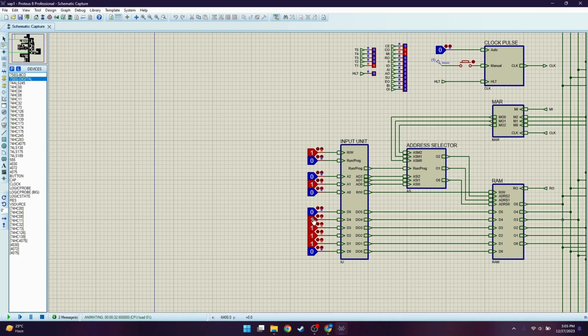Then we go to the next address location, and I will select the next opcode, which is 011. The next 3 bits don't matter. Still we are making them 011, which is the output opcode. Then we will write it on the RAM. Then we will go to the next opcode and select the halt opcode, which will stop the operation. Then we will write it on the RAM.